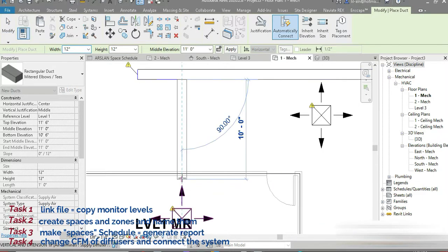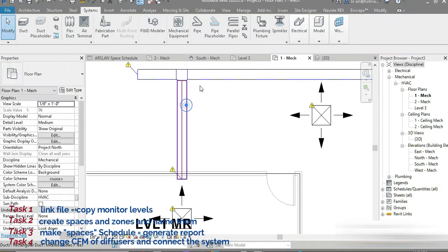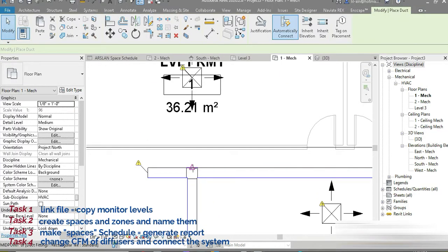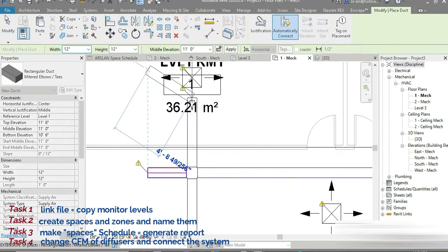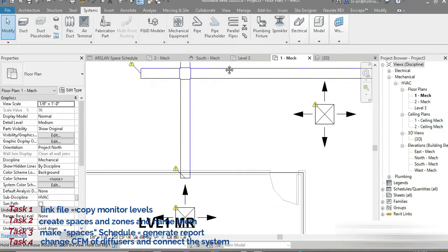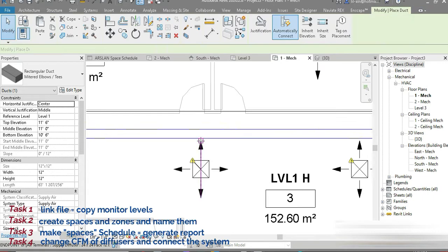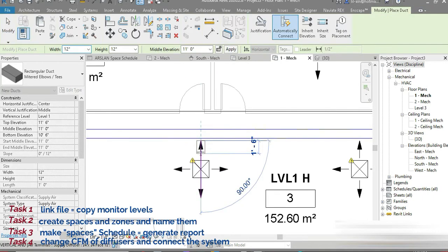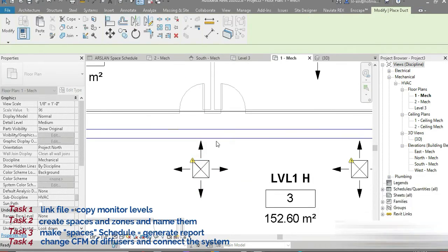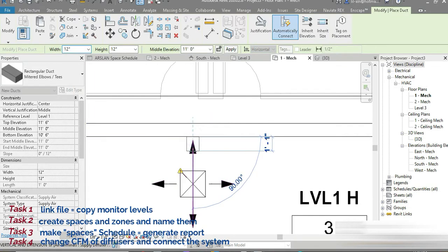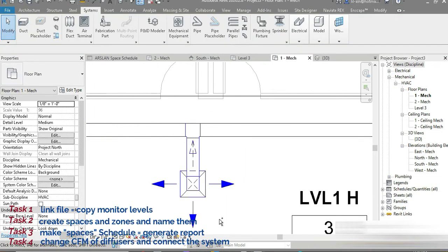So for example, click on this point right here, and click on this again. So CS, which is create similar, and click on this point right here. So remember, this is 11 feet and that is 8 feet. Okay, so you have to keep these points in mind. After that, press CS again to create similar, and okay, that's fine. So click on this point right here, go to control and Z.